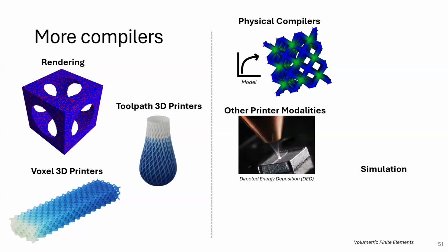So one of the key things to remember in 3D printing is we have a printing direction. So we're building layers like this across the z-axis. And yes, if you print that dog bone, you're always going to want to print it laying flat with the layers because between the layer bonding is a weak joint, right? So if I take this object and I pull on it like this, it's going to break a lot faster than if I pull on it sideways because we're going with or against the layers.